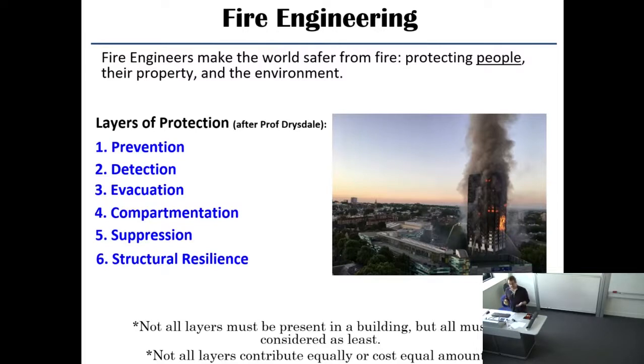This is very important. This is compartmentation, which is if we are going to fail preventing the fire, and hopefully we have detected and people are evacuating, we must keep the fire in what is called the room of origin. Okay? So don't let the sickness spread, because actually that's when you lose control. And an extreme case of this is Grenfell. It was not just getting out of the room of origin, it was getting out of the flat of origin, it was going actually out of the story of origin, and it was actually even going vertical, which is not even considered in the strategy to defend the tower. And the UK is very strong on compartmentation. Every country is, but the UK more.